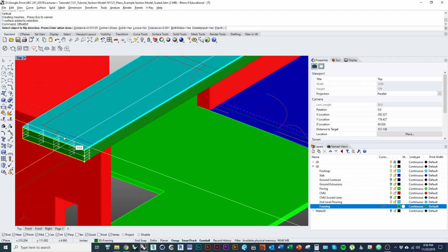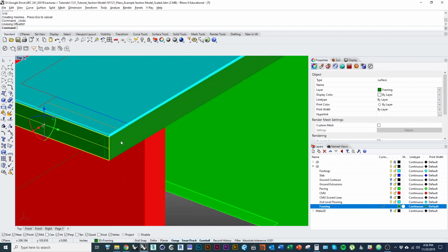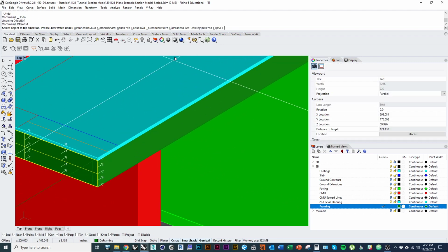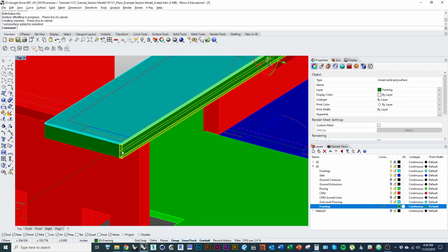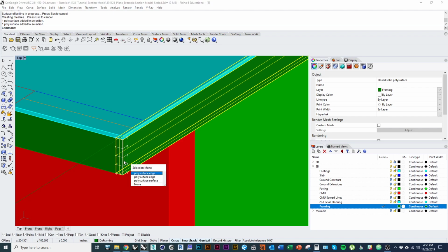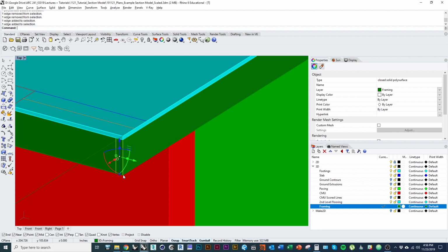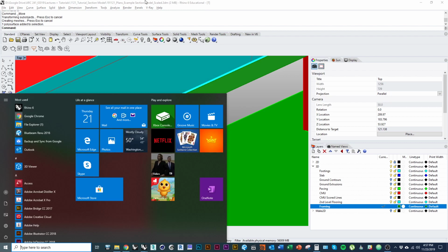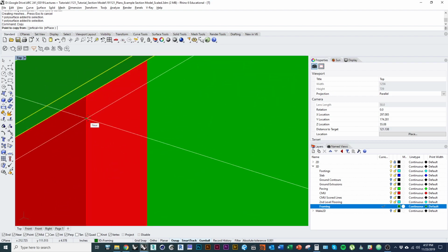All right, so then I'll offset this one, because I drew it right on the edge, I'm going to offset it just inward. So I'll reset the distance to 1/16. Gotta turn off the option for both sides. That didn't work. Turn it off, there we go. And so just like before, I can easily edit this guy by selecting the edges, and move it just in like that so that they're meeting at the corner. All right, and then I'll copy this one over.